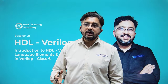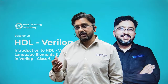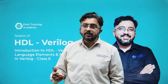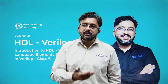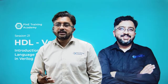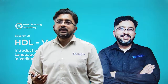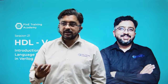Writing the code is very important, but verifying the design with the test bench is very important too. Because if you have 100 inputs and 30-40 outputs, you cannot force the constant value every time. So it's better to write a test bench for your design, give the values inside the test bench in the form of textual code, then simulate it and verify the design.